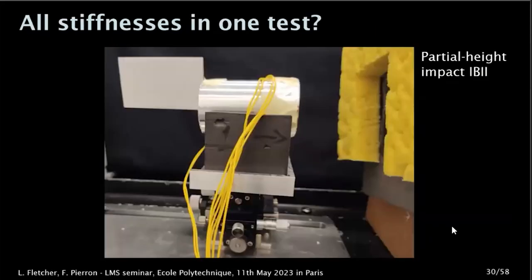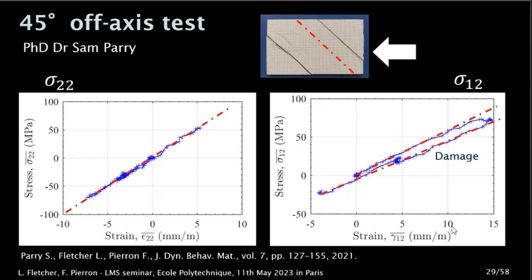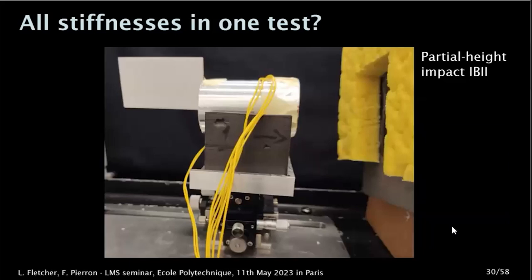The latest effort was to push it yet further. So here we've got the two components, 2,2 and 1,2. But can we get the 4 orthotropic stiffness components on just one single test? It's a bit more challenging, particularly for carbon composite, because getting the fiber modulus is a real nightmare because it's so stiff. On the other hand, the fiber modulus isn't very strain rate dependent, so you could just do a quasi-static test, probably enough. But for a glass epoxy, for instance, it might be interesting.